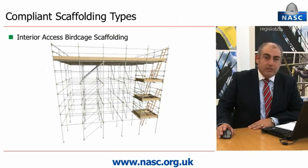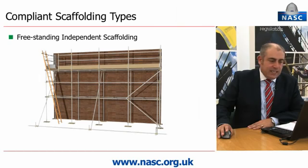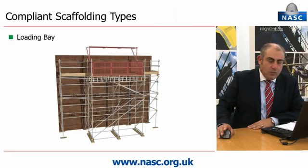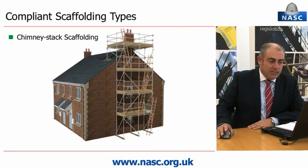We see the welcome introduction of compliant interior access birdcage scaffolds, tied put-log scaffolds, freestanding independent scaffolding, stabilised with butting transoms and ground rakers, loading bays with variations for 10 kilonewton or 15 kilonewton loading capacity. Ladder access towers are butted to independent tied scaffolds and chimney stack scaffolding.